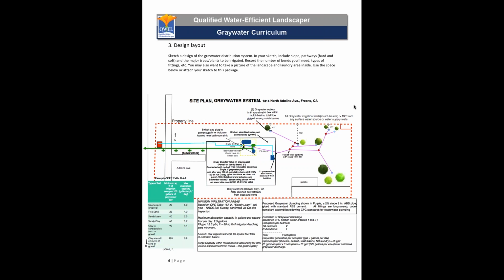And there are a couple of other notes on here about the plumbing assemblies, the type of three-way valve, and the backwater valve, the sewer check valve on the sewer side of the three-way valve, that's noted. We noted the kitchen sink is not connected, and some more details about the outlets, the address, and then down at the bottom we re-showed our design calculations for gray water production and our minimum irrigation field sizes.